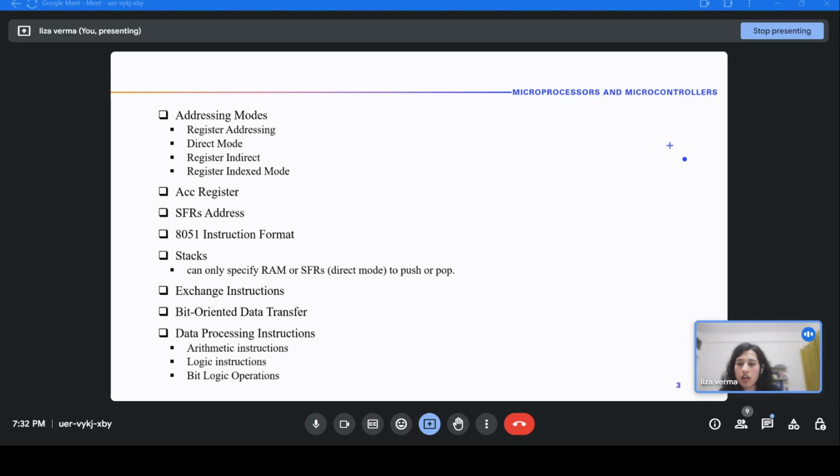Like in previous addressing modes, let's say in direct addressing mode, you said if I want to move the contents of location 60 to A, you'd use MOV A, 60H, right? So I'm just asking, why are we using MOVC here, not MOV? First of all, the address was 8-bit, right?